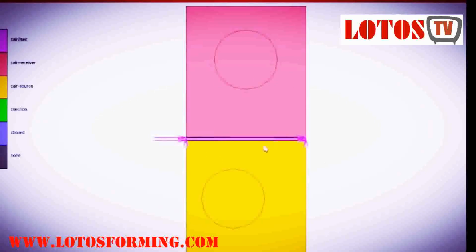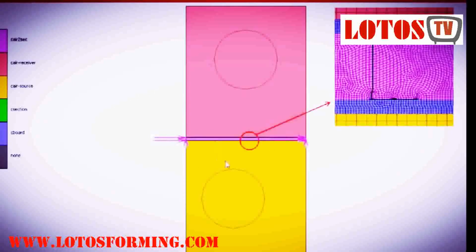And in between them is the board and the studs. If we look closer at the system of the board, we can see here, this is the stud. In this case, it is stud A that you can see. And then the pink color element here represents the air cavity in between the board, that is in light blue color here. So the air cavity connects to the stud, and also connects to the board, and connects to the receiving room and the source room that show a part of the elements here.